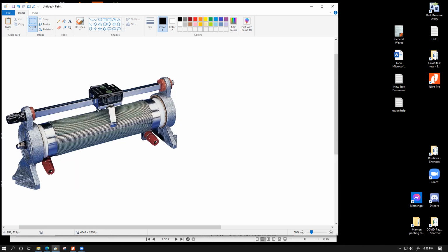One is over here, one on the back side, which you can slightly see over here. So these two actually clamp onto this coil of wire from two sides. And if we move this thing on this rectangular shaft, they can move around. And as they move around, these contact points actually remove some part of that insulation and can make electrical contact. If you wonder, this is how the electrical conduction happens.